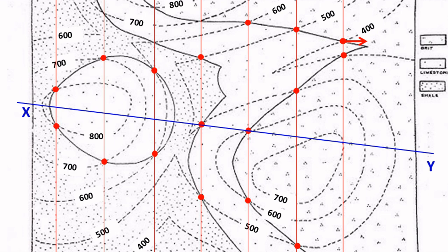For example, in the map, this point and this one both have an elevation of 800 meters. And the section XY is located inside the 800-meter contours in this particular area. So, the profile should show that this portion is higher than 800 meters but below 900 meters, as the section does not cross the 900-meter contour. Therefore, connect these points with an upward convex curve.